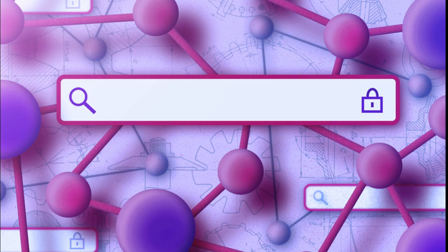Finally, they incorporated a heuristic technique that ensures SecureLoop identifies a schedule which maximizes the performance of the entire deep neural network rather than only a single layer. At the end, the search engine outputs an accelerator schedule which includes the data tiling strategy and the size of the authentication blocks that provides the best possible speed and energy efficiency for a specific neural network. When tested in a simulator, SecureLoop identified schedules that were up to 33.2% faster and exhibited 50.2% better energy delay product, a metric related to energy efficiency, than other methods that didn't consider security.